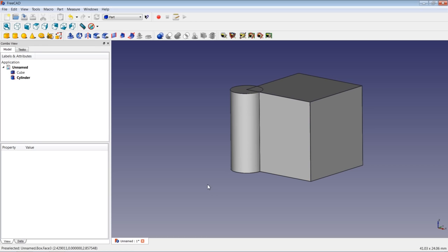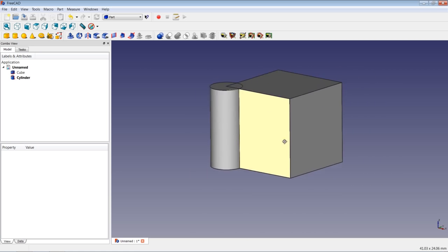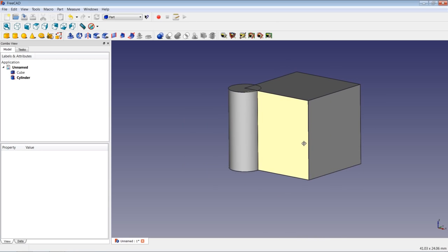Since I am in Blender mode, I will press down the Shift key and keep it pressed, and I will press the scroll wheel and keep it pressed, and you see that the cursor just switched to a special cross. If I still keep pressed the Shift key and the scroll wheel and move the object, I will pan the object around.